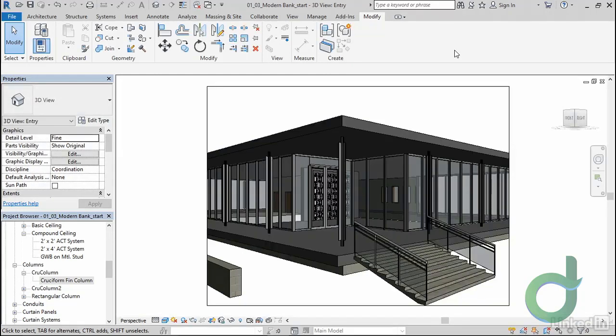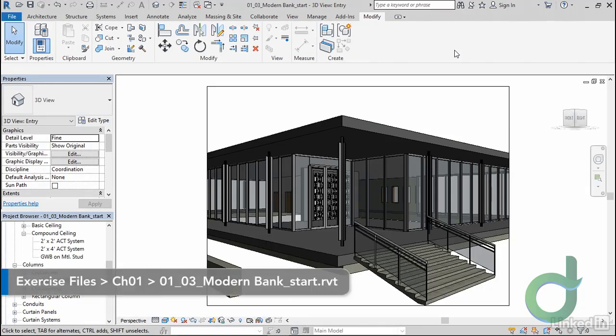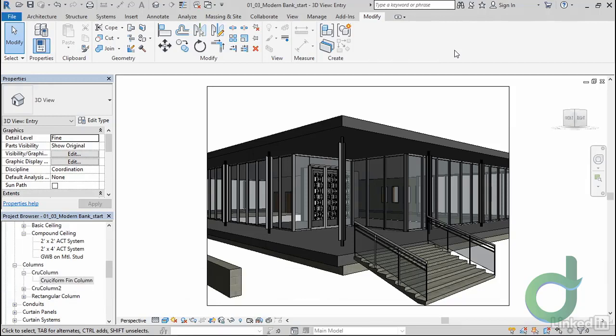When you're working in Revit and planning on taking your model out to 3ds Max for a rendering or out for a real-time simulation, it's a good idea, as I've stated, to break up large meshes. This is especially true when you're dealing with a mesh that may have holes punched in it, such as our ceilings here in our bank, which may get recessed can lights. The original has tall surface mount cans, but I'm going to recess some here over this screen wall. Later we can add other fixtures that are surface mount.